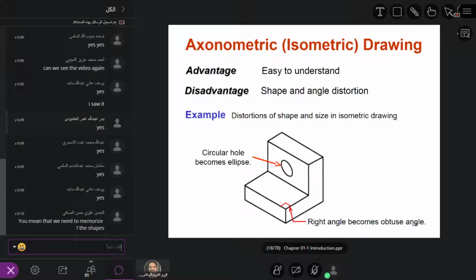Now you see here. This is a three-dimensional view. So obviously this should be axonometric, because axonometric means three-dimensional. Why is it a three-dimensional drawing? Because on a two-dimensional paper, this will give you the length and width as well as height. So these three dimensions are given in a two-dimensional paper. So that's why this is three-dimensional. We call it isometric drawing, or otherwise you can say axonometric drawing. That means the particular drawing will be given all the three dimensions possible.